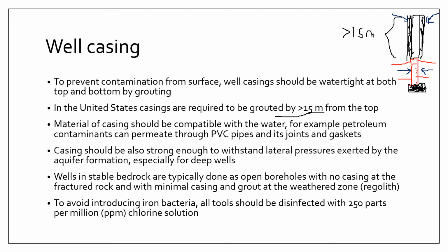Now, another concern in well casing is the presence of iron bacteria. These bacteria are typically introduced from the surface or from the tools that are used during drilling. And the practice is that tools that are going to be used for drilling should be disinfected by a chlorine solution.